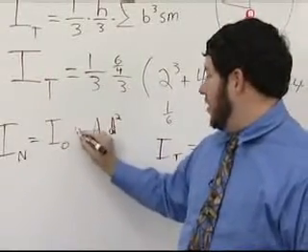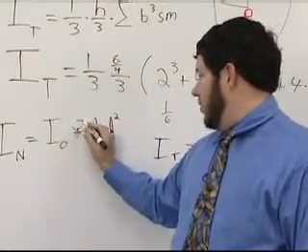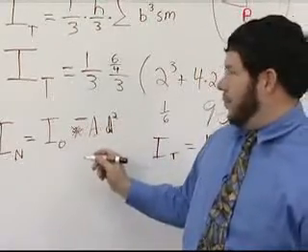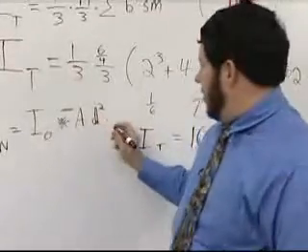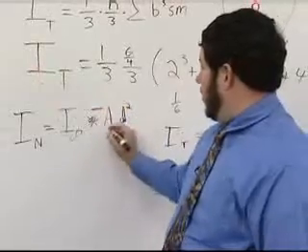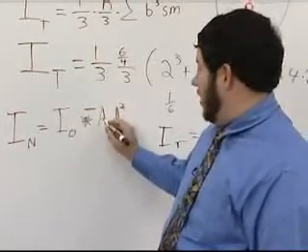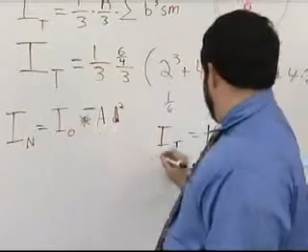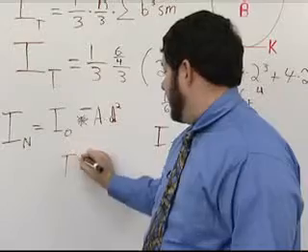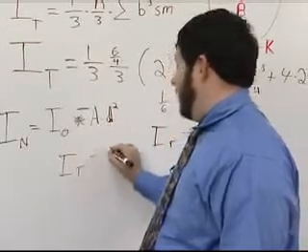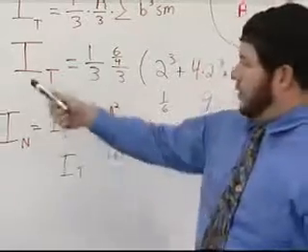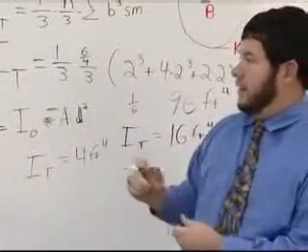So this plus sign goes away, and we use a minus sign instead. So the distance that we're moving is 1 foot, half of the beam. So our subtracted area is just the area, or 12 feet, 12 feet to the fourth. So our resultant IT is also 4 feet to the fourth, which agrees with the IT we previously calculated.